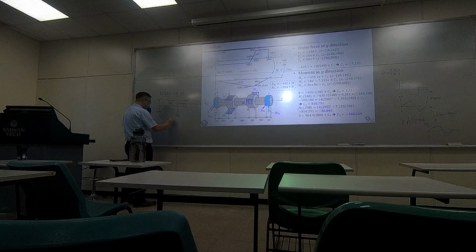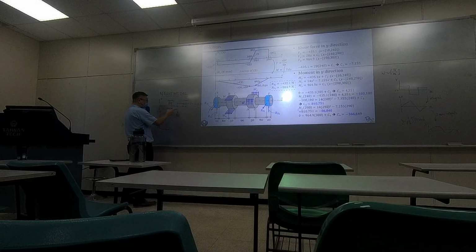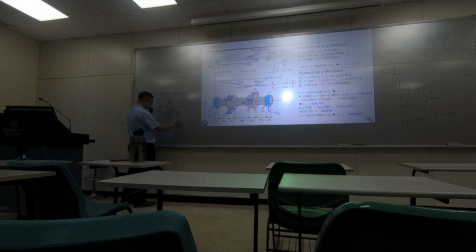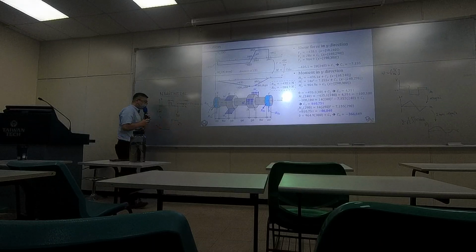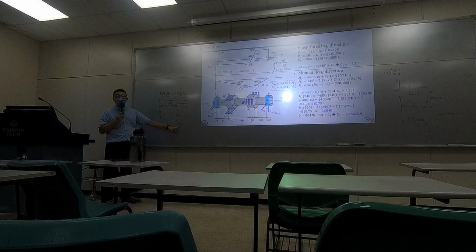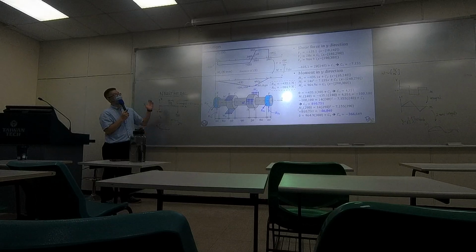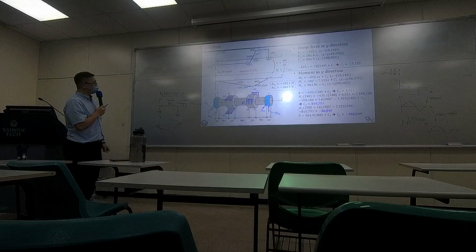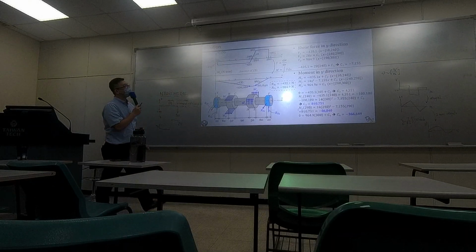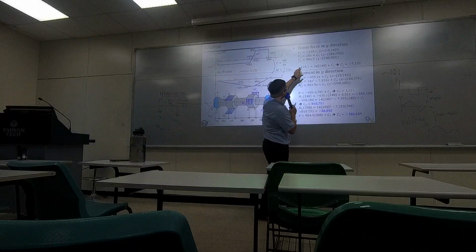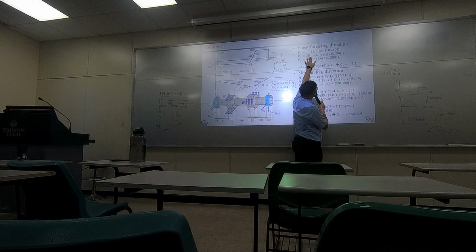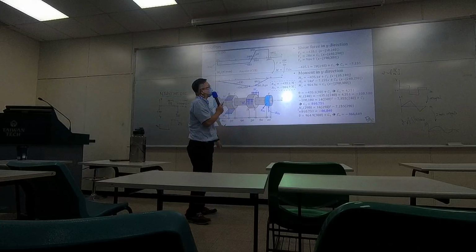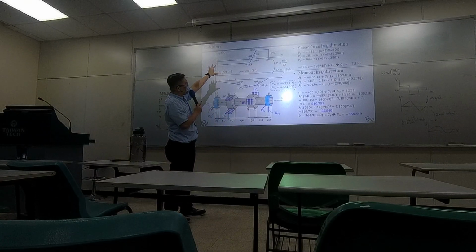And then from here, you continue to take a walk toward the right until you reach the right edge, and it's going down 965. If you do this and it doesn't reach 0, something was wrong. Okay. So I think that's the easiest way to get a shear diagram. And of course, sometimes you need to do some integrals. On the right hand side, I already gave you the integral equation, right? And sometimes you need to plug in to determine the coefficient. So that's how you get the upper part.